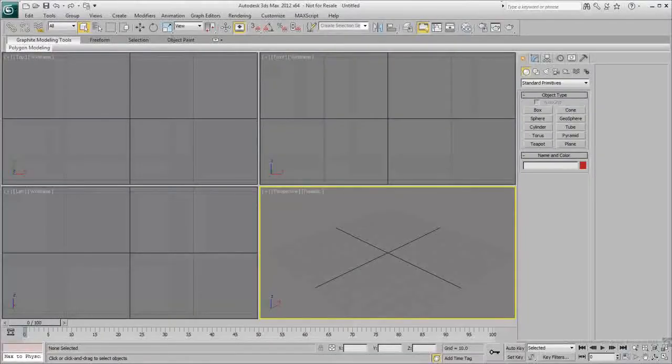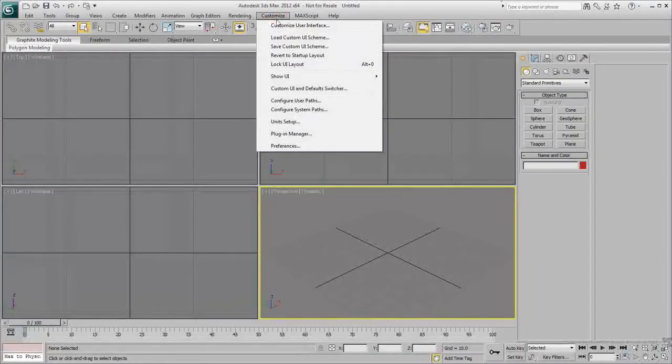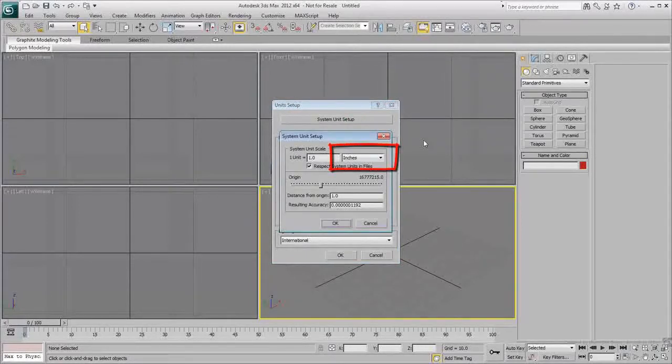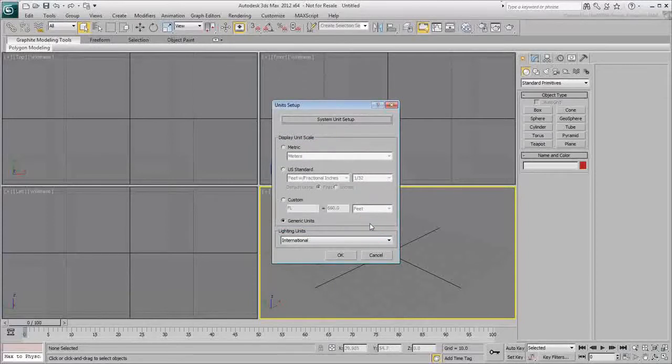In 3ds Max, your default system unit is set to inches. So some scaling is needed between the metric system from AutoCAD and the default imperial system in 3ds Max. Of course, you can set your system unit in 3ds Max to match that of AutoCAD, but leave that alone for now. You'll do the appropriate scale conversion at import time. Your display units, however, can be set to your liking. In this tutorial, use the US standard setup with the foot as a base unit.